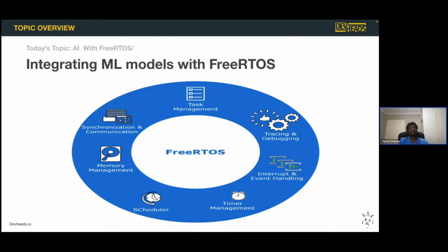Okay, I think this is more an illustration of why we need the real-time operating system and why we need it specifically in machine learning. So we need it to manage the tasks. One is for sensing how the mouse is moving. One is for moving the mouse movement data and putting it in an array or a queue. Another one is for taking from the queue and making sure that it's clean enough for the machine learning inference tool.